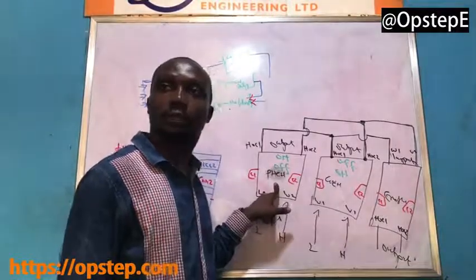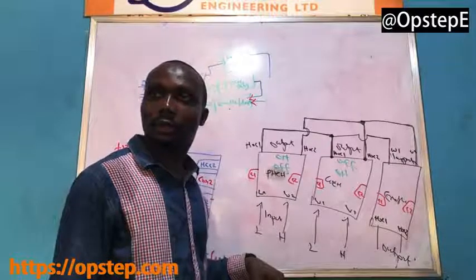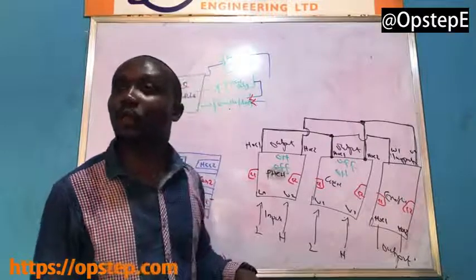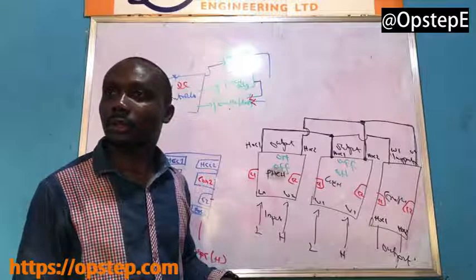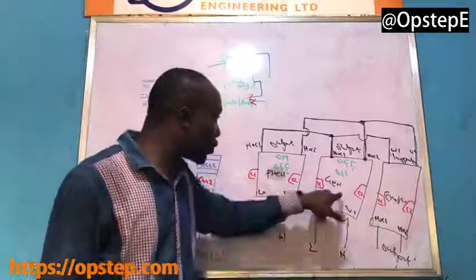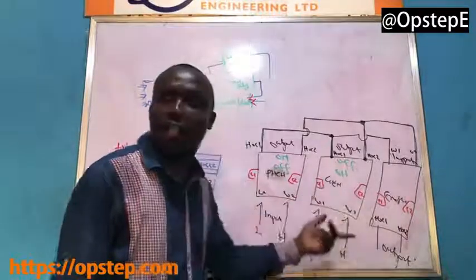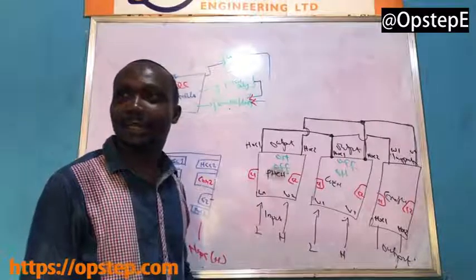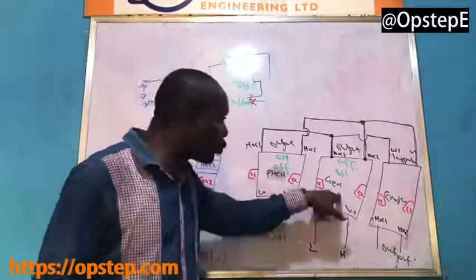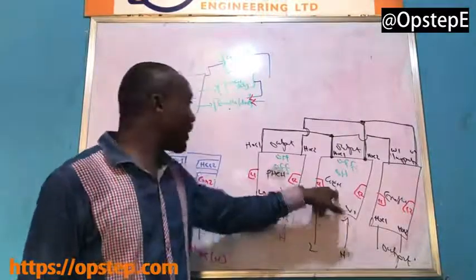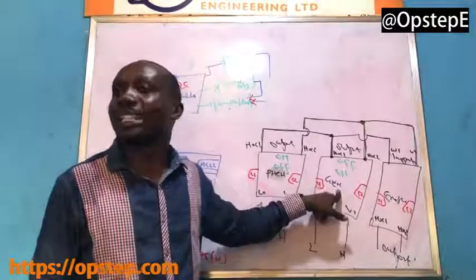So as soon as you receive the instruction for the generator coil to come on, it automatically turns off the NEPA coil. It will not. You are the one that will tell it to turn it off. So what if the user forgets to instruct the NEPA to go off first before I send the gen? You start the gen, but this coil is off, the generator voltage is just going to be there. Yes. As long as the coil is not on, it's intelligent. The coil of the NEPA is currently on. As long as this is on, this will be off. As long as this is on, this is off. It's already in its code. No two can come on at the same time. It's not your doing.